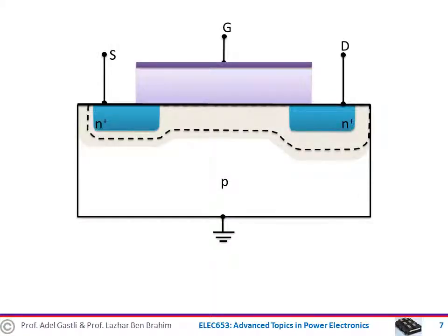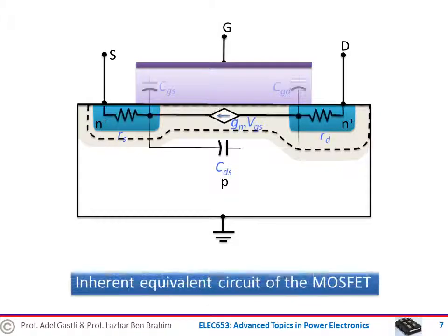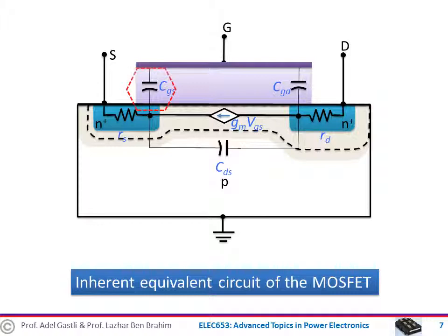As it was presented in the previous animation, an N-channel MOSFET is constructed as shown here. As you may know, different semiconductor materials develop virtual or parasitic capacitance between them. Therefore, we can represent the MOSFET electric equivalent circuit as follows. Therefore, if we want to establish an electric field between the gate and the source, we have to charge the capacitor CGS. And if we want to cancel this field, we have to discharge this capacitor also.